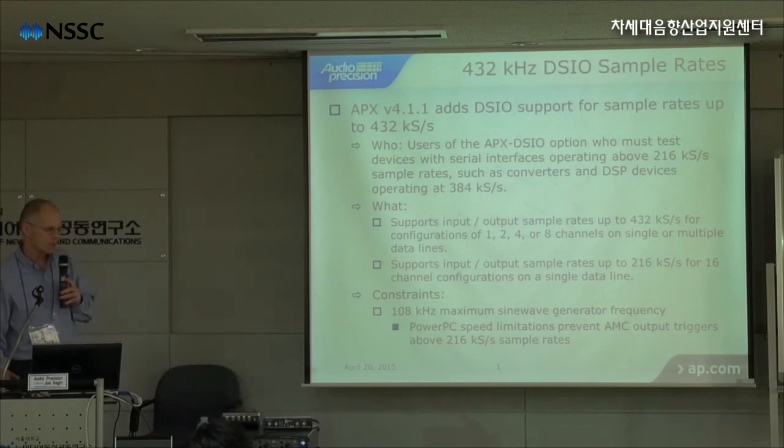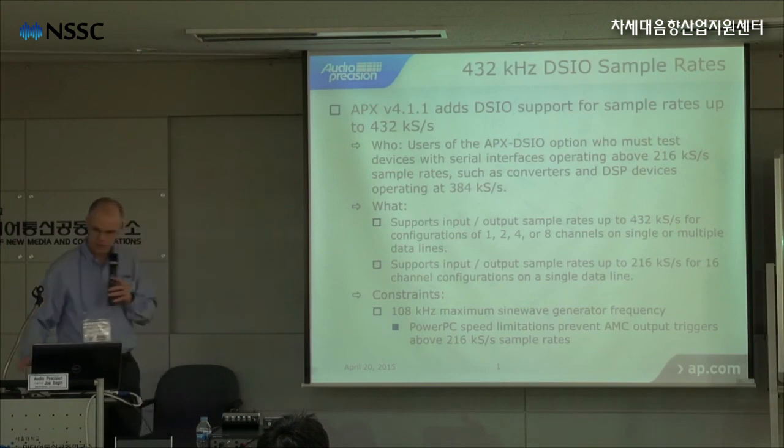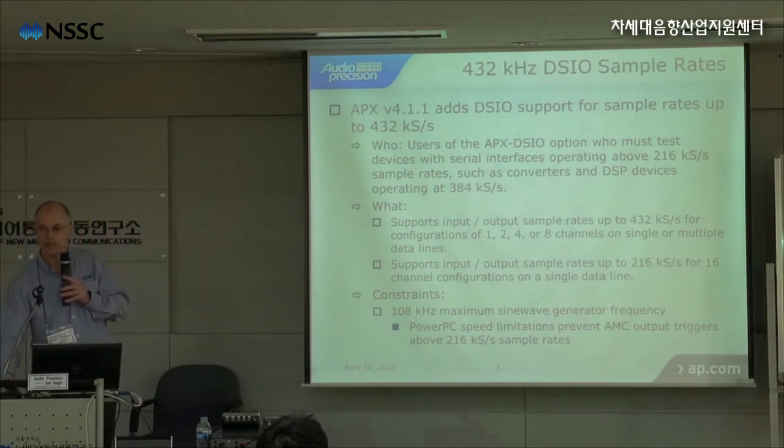There's a little power PC chip that generates the signals, and it can't keep up, so the clock sync on the back runs into trouble. So the generator is limited to 108 kilohertz.